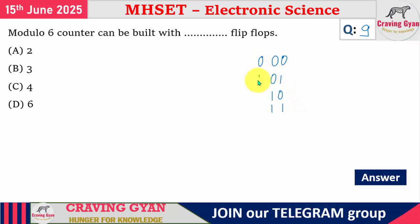But if I am making use of 3 flip-flops, how many states can I count? I can count 8 states. I can count maximum 8 states. More than 4 I can achieve. But here what they have given is modulo 6, nothing but 6 possible states can be realized with the help of 3 flip-flops. For the 9th question, the corresponding option is option B. Nothing but 3 flip-flops are enough.